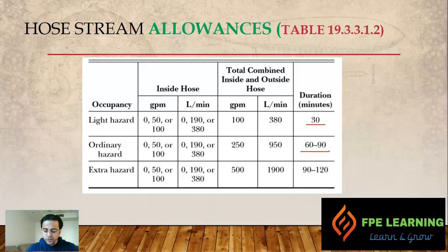Water allowances for the outside hose shall be added to the sprinkler requirement at the connection to the city water supply, right? Or city water mains or a private fire hydrant, whichever is closest to the riser, right? One more thing, NFPA says that when hose demand is provided by a separate water supply, the sprinkler calculation need not include the hose allowances, right?